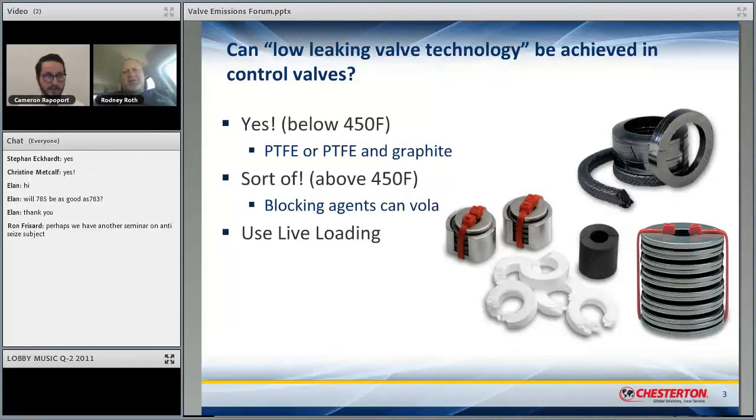Well, first of all, the ISO test standard is a valve test and a valve and seal combination test. So you're not just testing the packing or the stem seal products, you're testing the valve itself in ISO 15848-1. In the API 622 test, that is a packing only test, and it's designed to be done in a fixture. It's always the same, so all the data is always comparative.